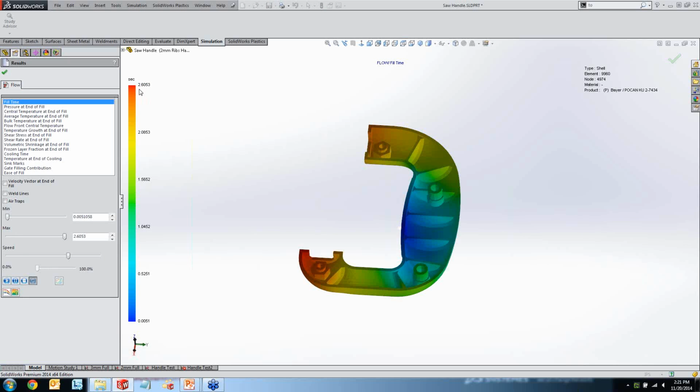The one thing I really do notice here, though, Dan, that we didn't really anticipate is it actually changed the fill time. Because of the smaller cavities, the smaller thicknesses, it increased the amount of pressure of the fluid going through there, or the plastic flowing through the model. So it actually shot it in there a little bit faster. We're down to about 2.6 seconds instead of 4. Again, just like with the material cost, shaving off almost 1.5 seconds of this design is really going to improve your end result. You're going to be able to make 5,000 of these a lot faster if you take 5,000 times a second and a half.